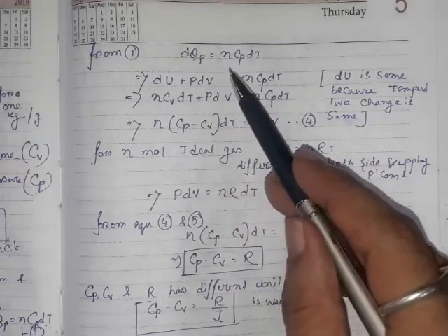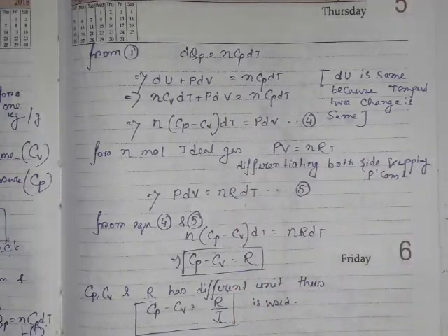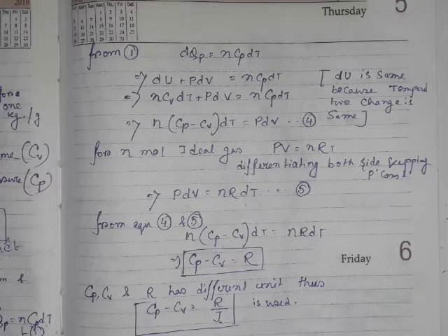Because in both cases, the constant volume case and the constant pressure case, you increase the temperature of the gas by the same amount dT, so the internal energy for both cases will be increased by the same amount, because the internal energy of an ideal gas is only a function of temperature.